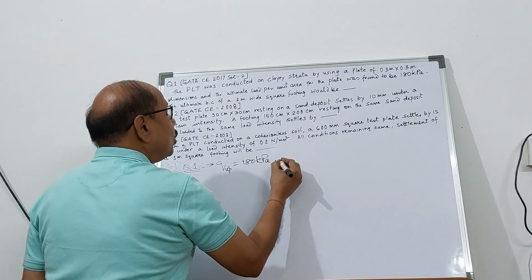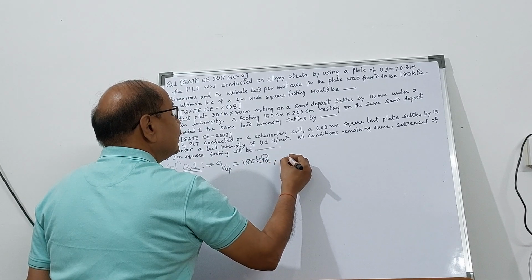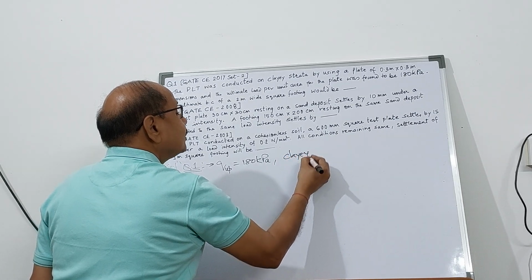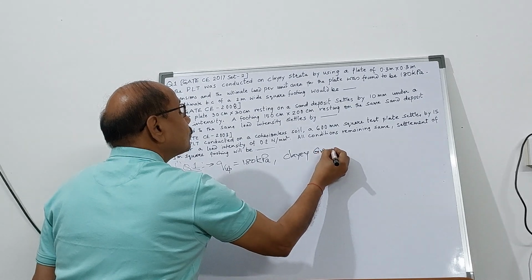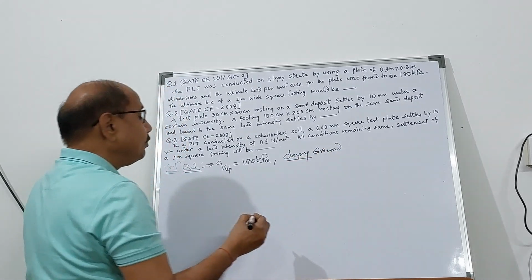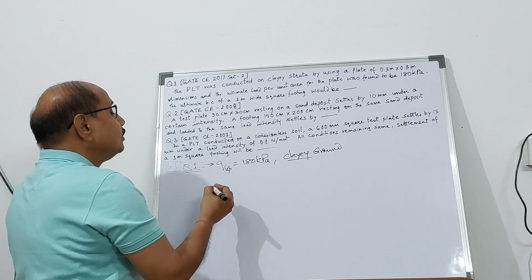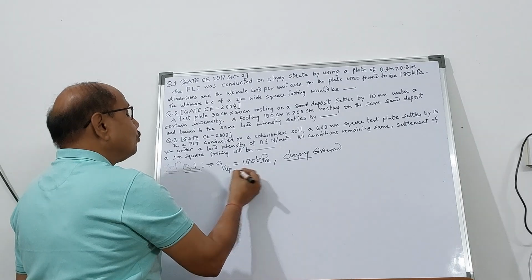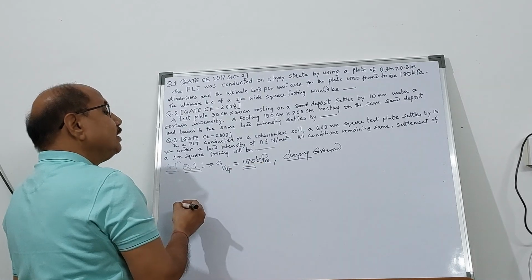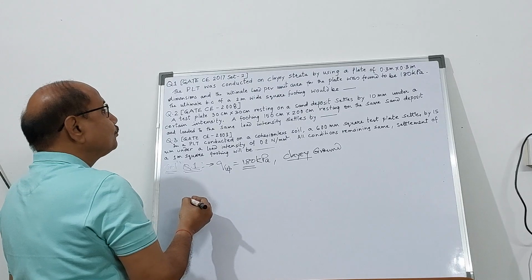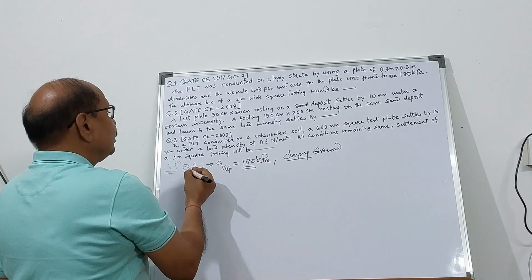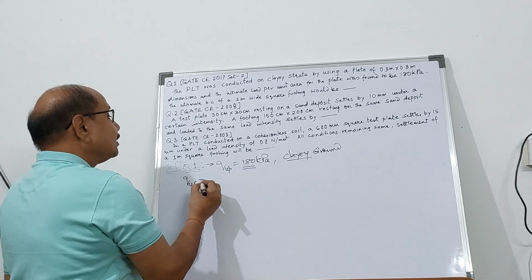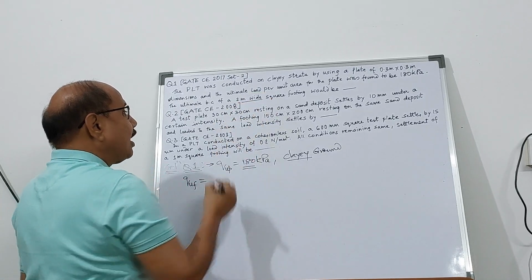And very important is the properties of the ground. So the ground is clay ground. If it is clay ground, the bearing capacity is independent of the size of the footing. The plate size is already given, 0.3 meter by 0.3 meter, and this is the ultimate bearing capacity from the plate load test. You need to find out the ultimate bearing capacity of a footing, whose size is given as 2 meter wide.